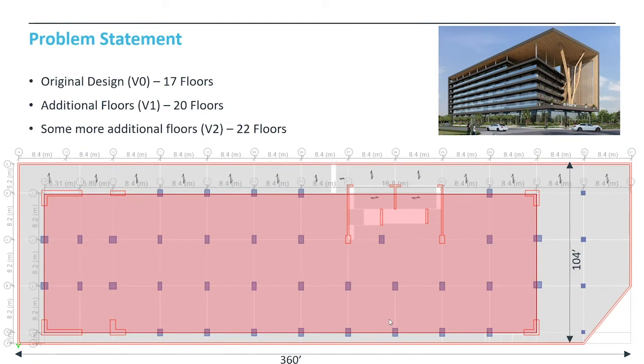What about erection tolerances, like out of plumbness and stuff like that? Obviously, there are some. How did that come into play when you were sizing new sections? Yeah, erection tolerance. Since the building was already constructed, they had to maintain the verticality only from floor to floor. The new additional bars, we had asked them to drill through the slab, or in one case, as you see here, the concrete or slab in the vicinity of the column, and that helped to maintain the verticality of the dowel bars, as well as the verticality of the shuttering and the entire cross section of the column as a whole.